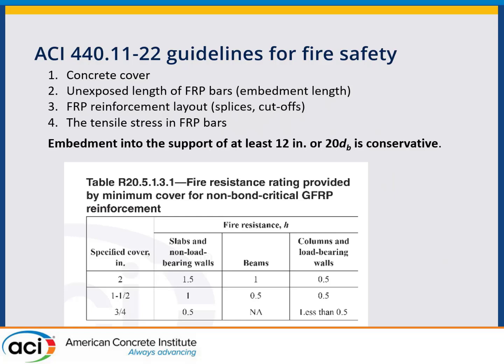I do think that in many configurations of slabs, particularly if you have edge beams or columns you can anchor into, you can largely achieve this without doing anything else. Maybe look at how you're laying out your reinforcement, make certain you have lots of bars in your middle strips, and if you have drop panels, etc. But it's going to be hard if you don't have drop panels or other things like that.